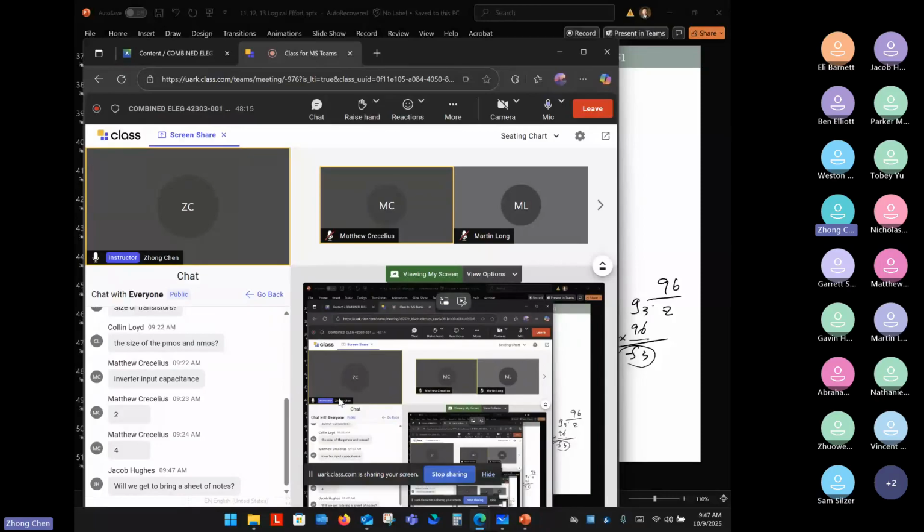So the T rise and T fall we have discussed using the RC delay estimation. That does not belong to the logical effort, right? I'm assuming that is what the question is going to ask. Remember, that is the chapter you need to go back to, the RC delay model. If it is the rise time T rise, that means the output is rising, which means using the PMOS to turn on the output. So you need to analyze the PMOS path.